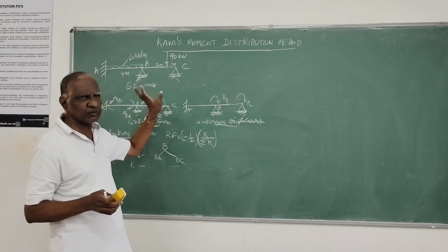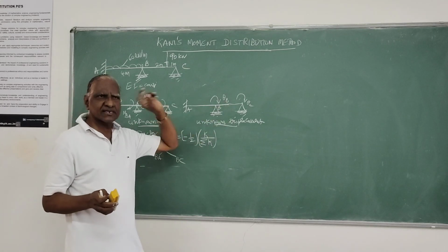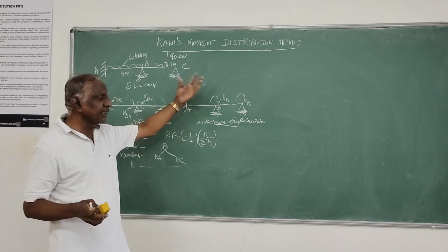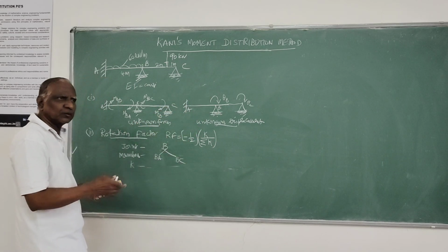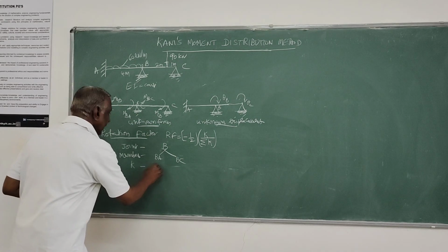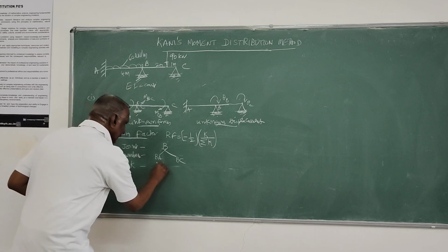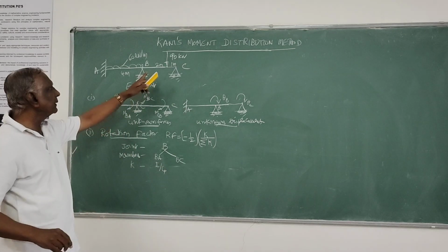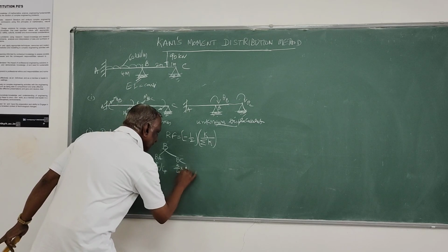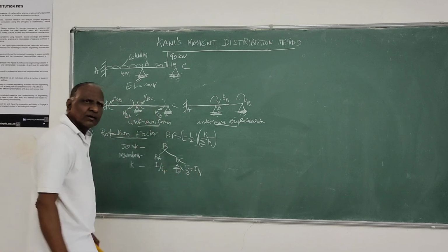Whereas for AB, one end is fixed, the other continuous, it is 4EI by L, for this it is 3EI by L. Instead of the absolute stiffness, we can take the relative stiffness value, which is I by L and 3/4 of I by L. Here, for BA, it is I by L, L is 4. For BC, it is 3/4 of I by L, L is 3 meters, that's also I by 4.